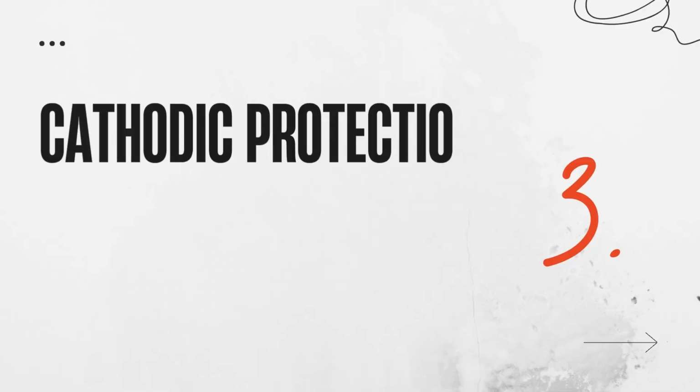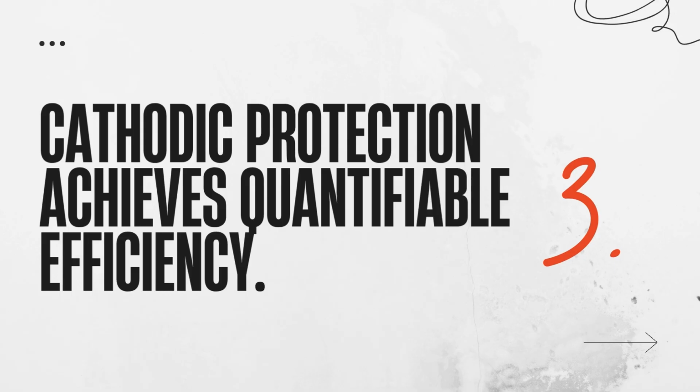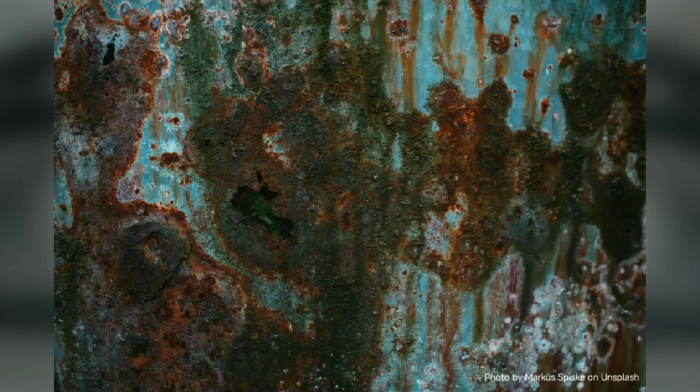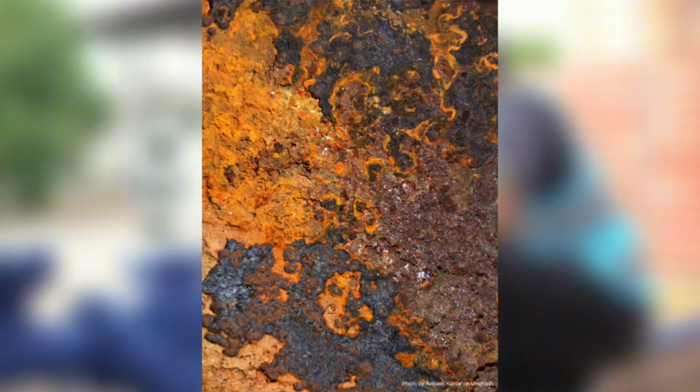Cathodic protection is the most effective method of stopping oxidation. This is achieved in two ways. Sacrificial anode, galvanic coupling with a more active metal, achieves superior corrosion reduction, and ICCP, applying an external source, reverses the polarity of the structural metal, forcing it to become the cathode and stopping spontaneous oxidation.